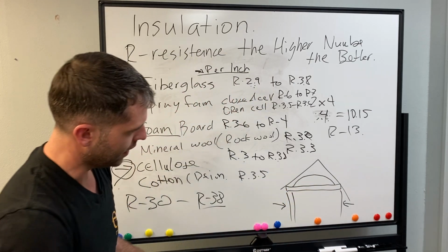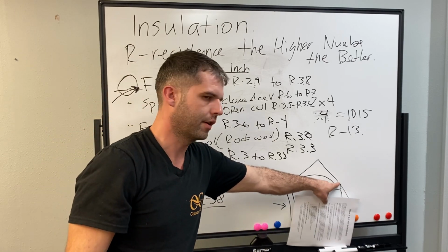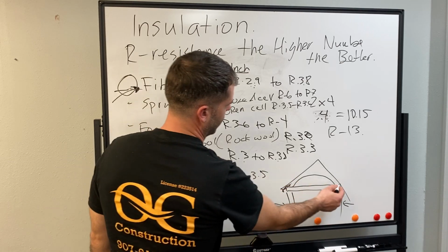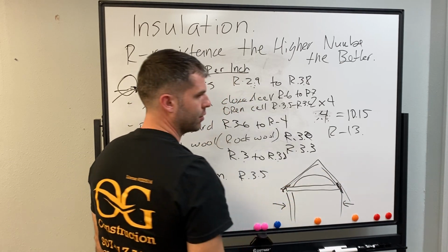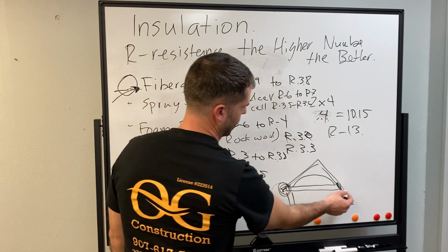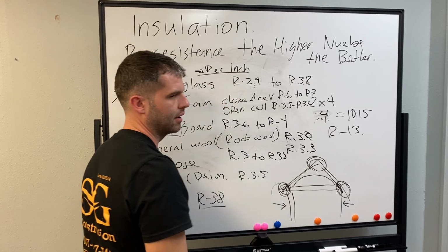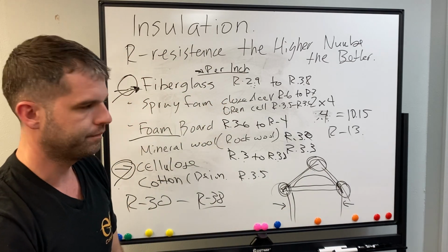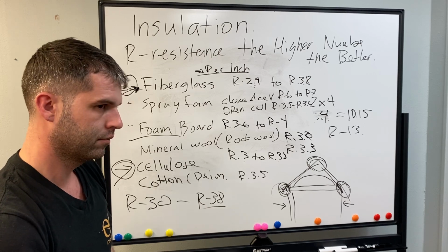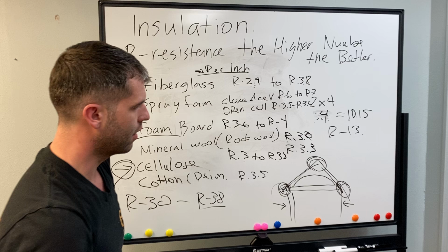It is very, very important to not go to the eaves, right there at that corner, because if you close it up, this won't breathe, okay? And what will happen is this will start condensating, and this inside will start condensating, causing mold. Why can't it be closed? Because it condenses and the condensation leaves a lot of humidity. It needs to breathe, air needs to come in. Okay, so it's very, very important.